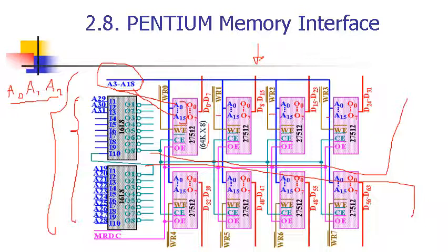All right, the rest of your address bits in this Pentium, we have 32 address bits: from 0 to 2 for selecting a bank, from 3 to 18 to select a memory location, from 19 through 31 to enable all 8 banks, to select all 8 banks, and specific banks will be dealt with depending on your write strobe.